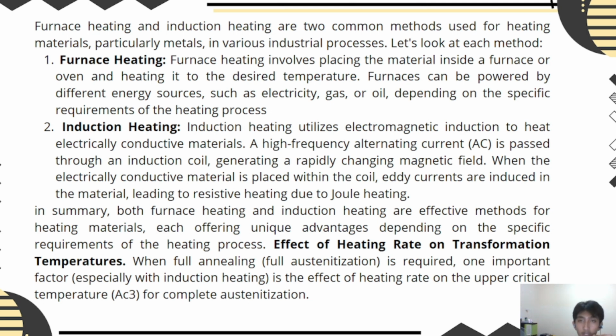Induction heating utilizes electromagnetic induction to heat electrically conductive materials. A high-frequency alternating current, or AC, is present in an induction coil, generating a rapidly changing magnetic field. When the electrically conductive material is placed within the coil, eddy currents are induced in the material, leading to resistive heating due to Joule heating. In summary, both furnace heating and induction heating are effective methods for heating materials, each offering unique advantages depending on the specific requirements of the heating process. Effect of heating rate on transformation temperature.